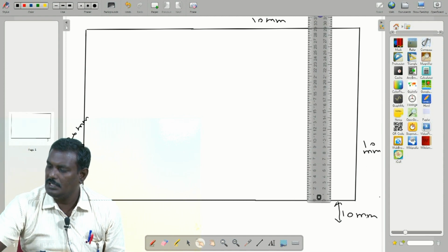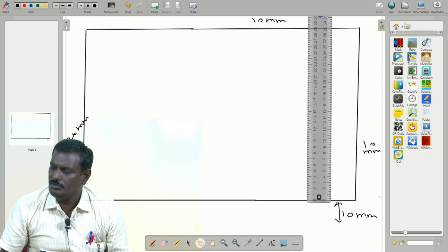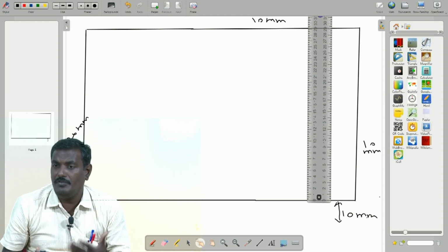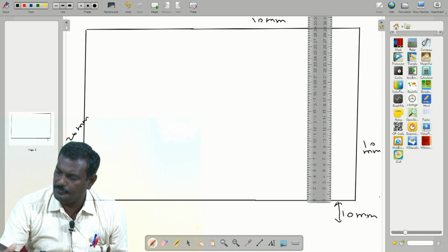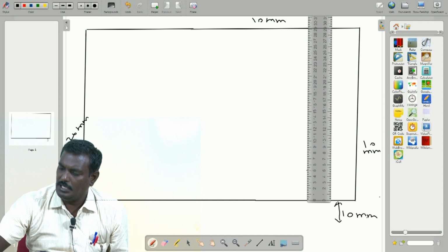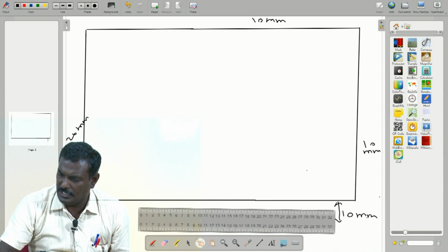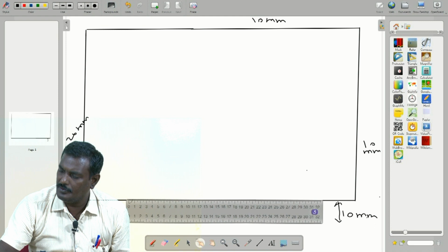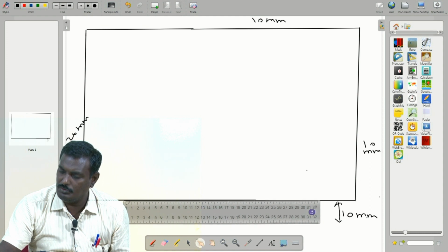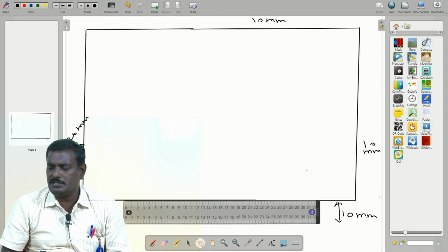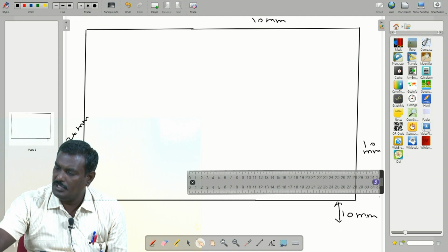Try to see, measure 90 mm. That is actually more, is it? It is very big. So it is enough to take 50 mm, we have to shorten it. Why should we go for more? So 50 you have to take, then put a dot. Now this scale again bring into original position, that is parallel to this. Set your mini drafter scale parallel to this, any one scale set parallel to any one of the border lines. Then draw a horizontal line for the height of 50 mm.